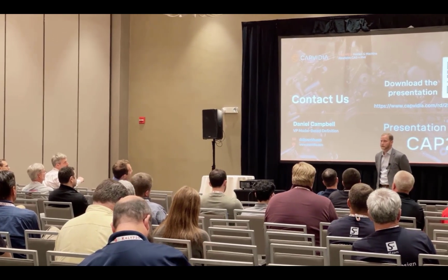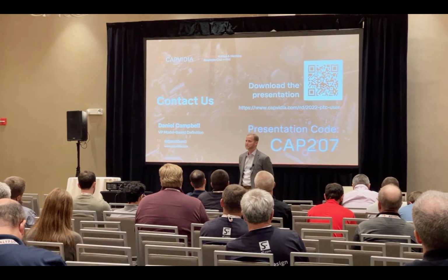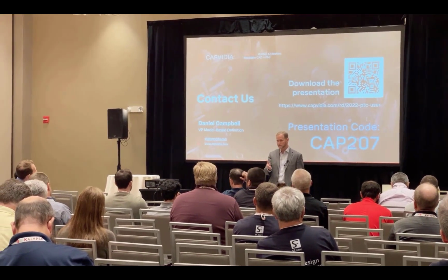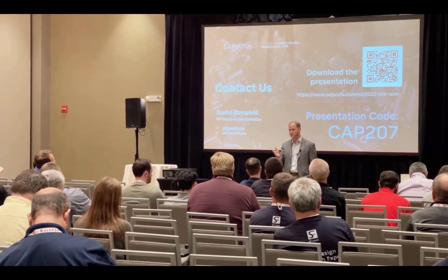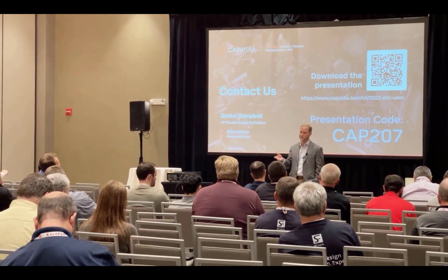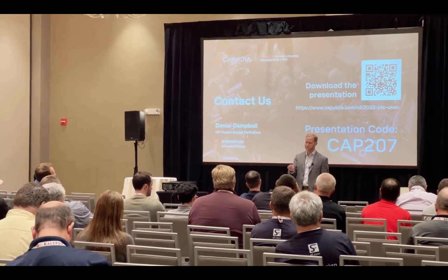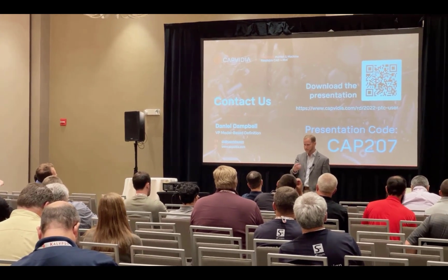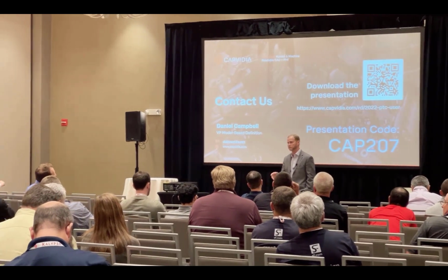I think, yeah, in a way, yes. It's kind of in a gray area between dimensional and non-dimensional. But I think that's exactly right. You're not going to measure that on the CMM, so CMM software is going to ignore that. So it's not about reading a surface finish tolerance into a CMM. But a surface finish annotation in Creo is a semantic entity that has all the information related to what the tolerance is and also what surfaces are controlled by that particular entity.